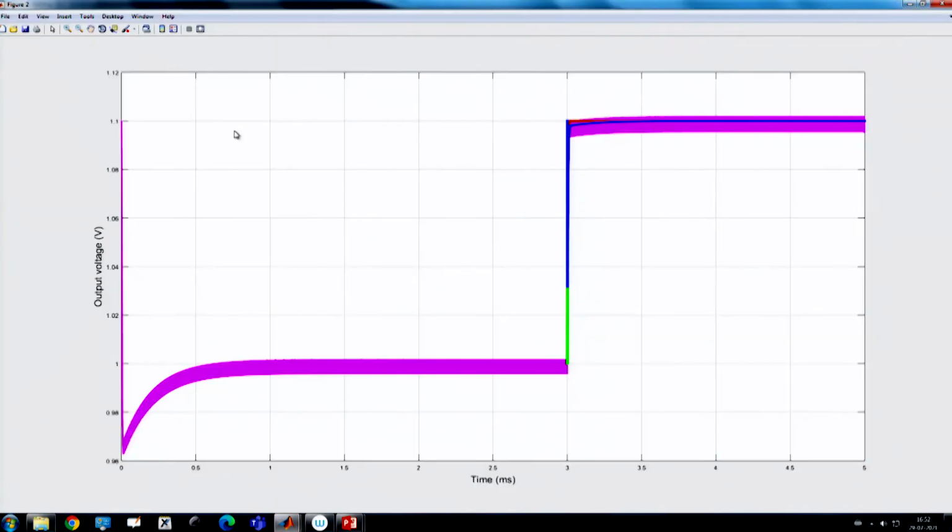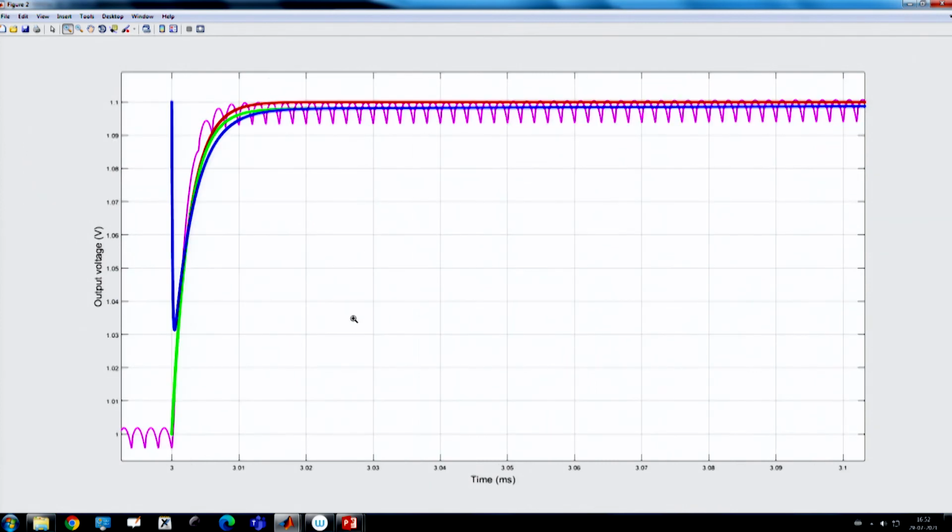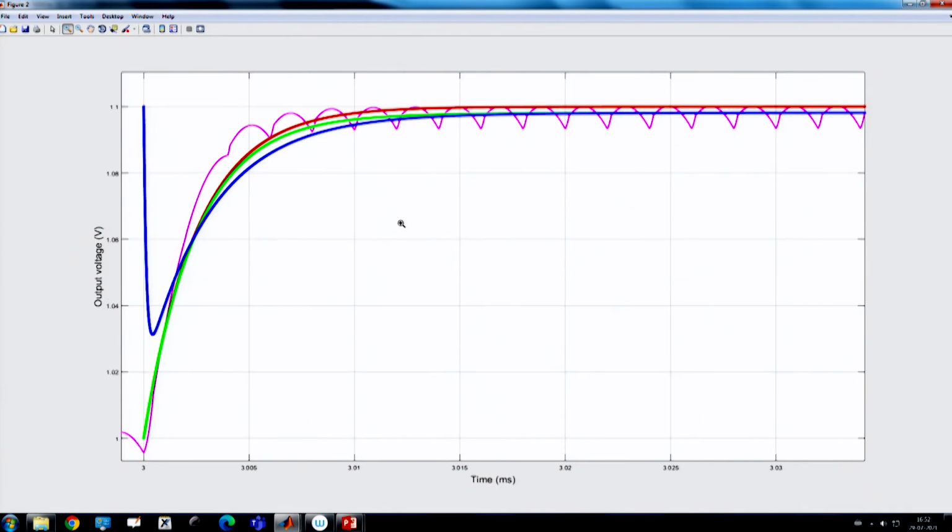So, at 1/8 they match somewhat better, that means we can push the bandwidth a little higher. In voltage mode control we got 110. So, in current mode control we can go like 1/8 or so, right, the bandwidth, and you see the models are matching reasonably well.